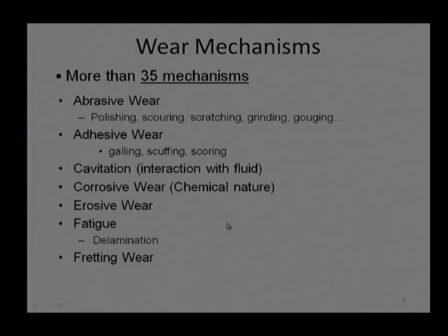Similarly, there is corrosion wear. There is a combination. Corrosion happens because of chemical action. It increases the porosity of the surface, and if there is a mechanical action on that, naturally there will be easy wear out of that surface. Loose particles, or we say that the porous layer, will be easily removed by mechanical action. So, there is a combination of chemical and mechanical, and by and large we say that wear is mechanical. That is why I have written here that it has a chemical nature. That means initiation happens because of the chemical action, and finally removal of material happens because of the mechanical action.